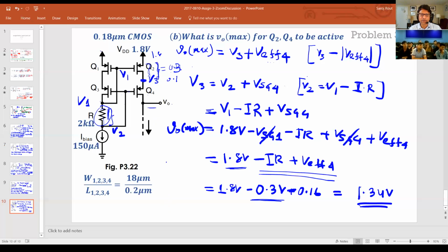So I think what I'll do is in the problem, I'll make this an NMOS. I'll just invert this and make it an NMOS, and I'll give you the solution. Definitely take a look at it, because that'll make it clear, because we had the NMOS simple current mirror. I'll show this with the NMOS, and that I think will make it clear. So I'll put the numbers in the solution, and you can see clearly why it's called a wide swing current mirror, and it saves you some headroom.